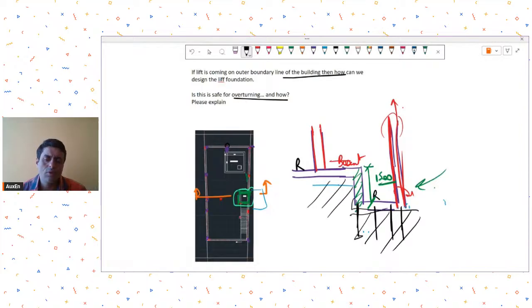So these can be a few options in case this region of your building is subjected to very high moments, because of which you are unable to manage the bearing pressure. Another way, of course, can be to thicken the raft for better load distribution. Generally around a lift you will not see a lot of issues, because it's not loaded very heavily, though these columns might be. So it won't be much of an issue. If it is, then you can come up with these solutions.